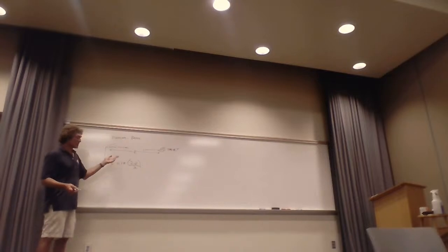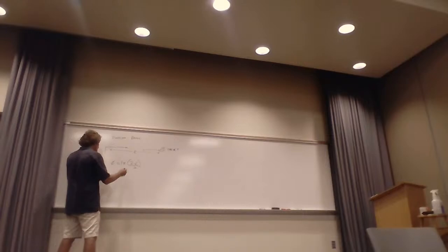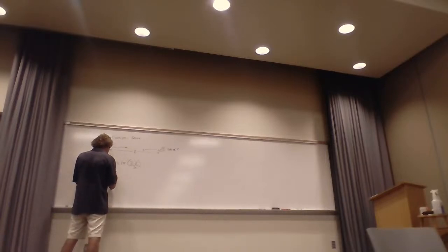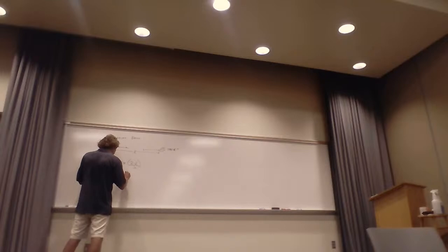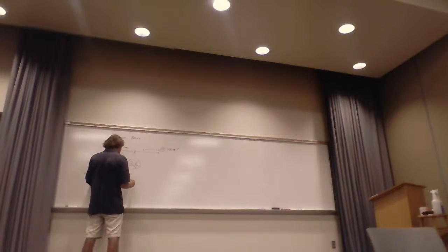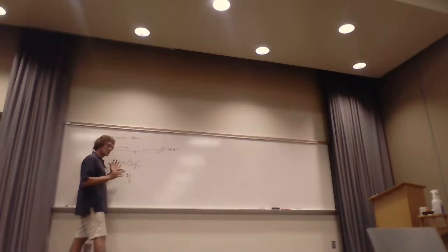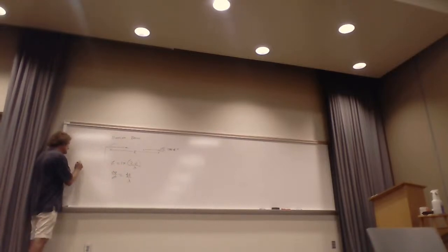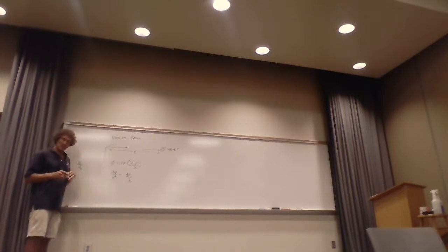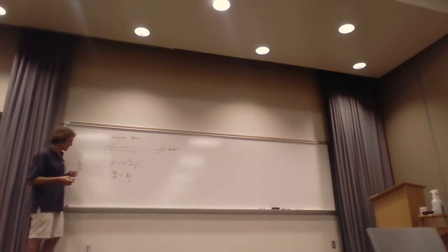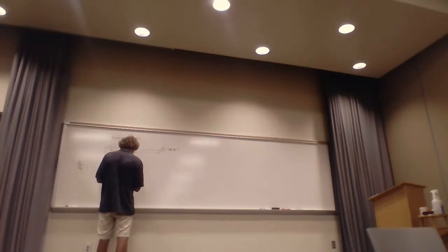So I'm multiplying by 2 pi so I have it in radians. Now when I take a time derivative of this, I have 4 pi over lambda. Lambda is just c, the speed of light, divided by the characteristic frequency f, so c over f would be lambda. You could call it lambda naught because it's assuming motion doesn't affect this wavelength. Times dr/dt. Y'all with me on this?